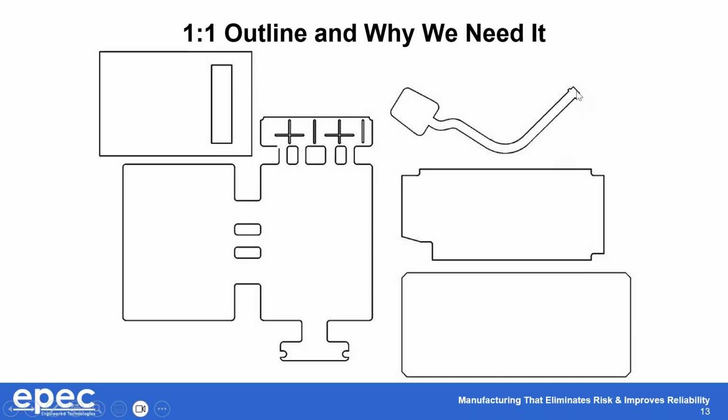Again, another flex board with a component on the end. The only place to populate this board is here in this odd shaped area. Another outline with some gold finger connector on one end, but a cutout on each corner that are keep away areas. And even this one is not perfectly square. We would need to know about these corner chamfers so we don't bring any components out towards this edge.